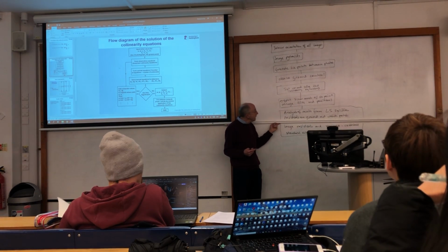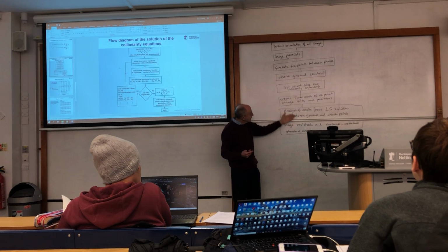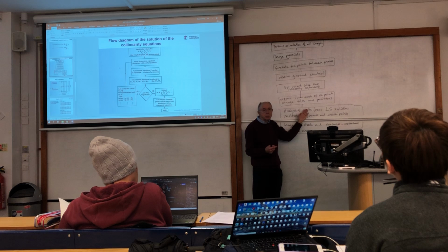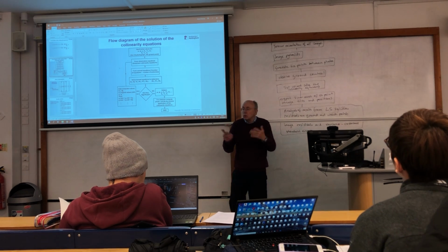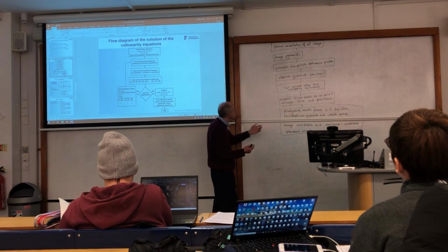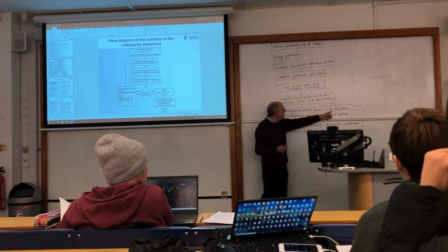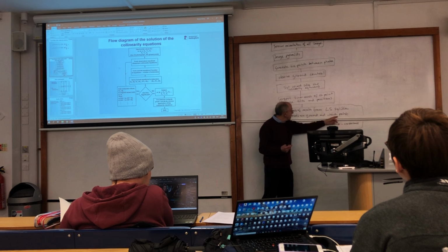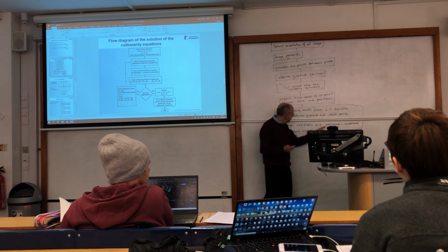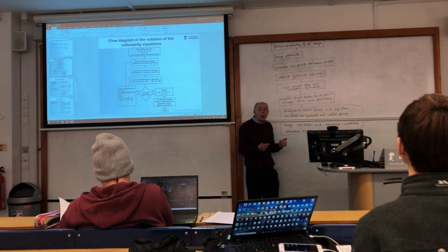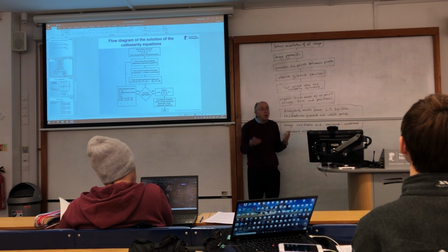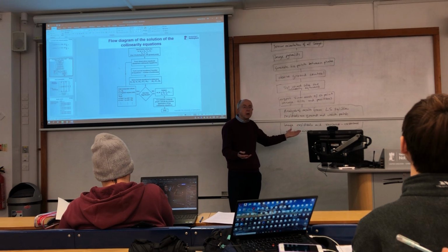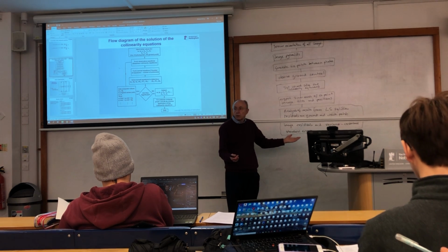Here I've tried to add in a little bit more because I thought it might be quite helpful. Again, I could have just put here analysis of results, and that would have shown me that you know the procedure. But if I put here, from a least squares solution, residuals on ground control, checkpoints, image residuals and variance, covariance, standard errors, all of a sudden you give me a lot more knowledge, showing your understanding, and you basically only put a dozen words on the paper.